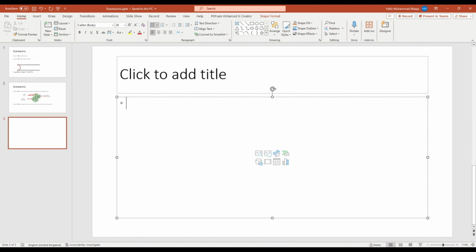Let's write our expression over here by writing our requirement. As I said, we want to control the temperature of the battery cell. Let's call it target temperature. So we need a target temperature, let's say 40°C. Then we have our initial flow rate. Let's call it flow initial. I would start with 2 gram per second.